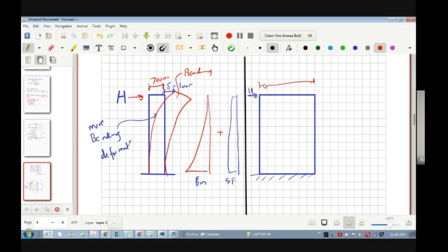Let's say this is 2 meters, 2000 mm. That means it will not bend like this. You can imagine also. It will be almost linear like this. The delta will also be less and there will not be bending curvature, but it will have a translational, or we can say line-wise deflection. Okay. See this.